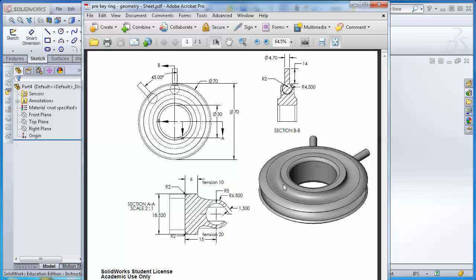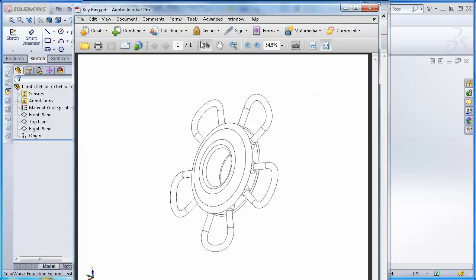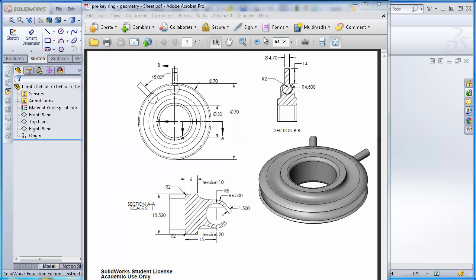This is actually a multi-body part in that we're going to make a pulley-like thing that looks like this cross-section, and then it's going to have these spherical features with a rod protruding, and we'll use a pattern to make a couple of them. So once we've created that, I want to turn that part into something that looks like this by collecting those protruding parts with a swept surface or swept solid, and then using patterning to make several copies.